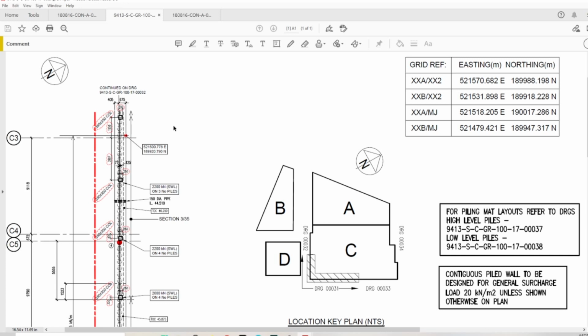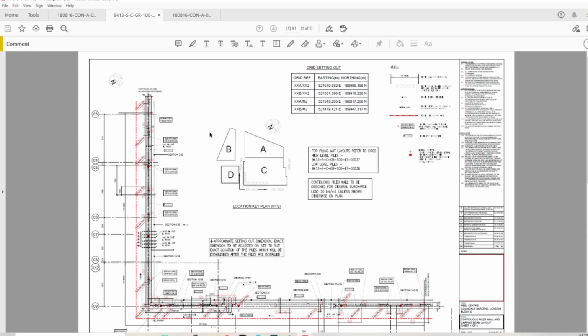And as you could see for block A, actually, you had this information on the GA drawing for the pile cutoff level, but you didn't have information about the columns. So you can see, you can expect different stuff while different designers are covering the job, really. But that's how we engineers do the job. We need to make sure we can get this information, and if it's not enough, we need to make sure we're going to RFI for it. We need to ask questions. We're going to collect all information, and we're going to be good to go to keep the job running.